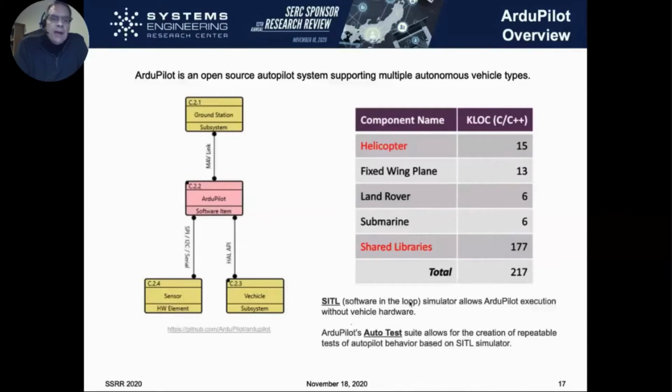And within that software-in-the-loop environment, there is also an auto test suite that was provided, mainly there for regression testing of ArduPilot as features are added. It's a Python-based scripting environment where you can put a UAV through the motions of flying different routes and monitor the behavior.